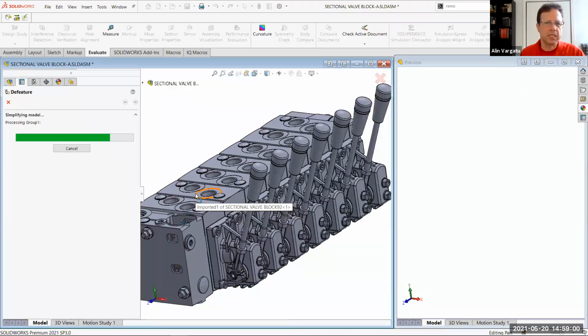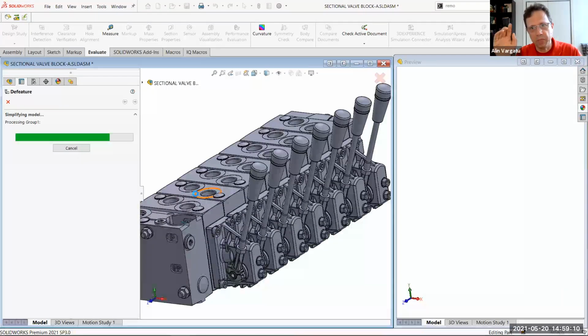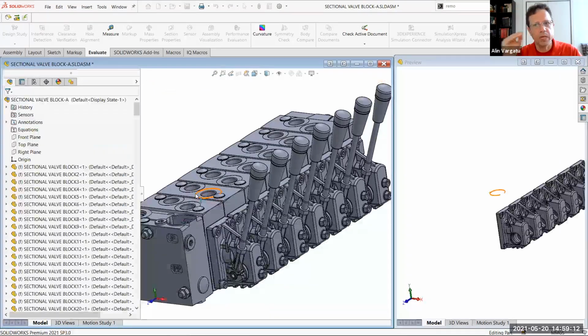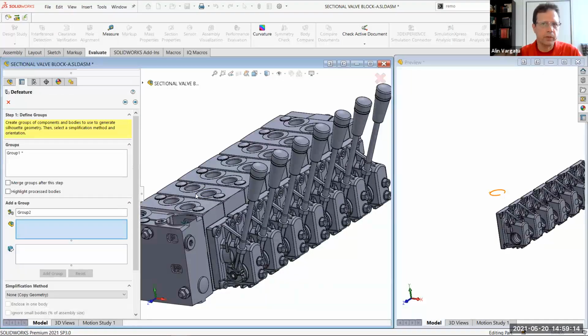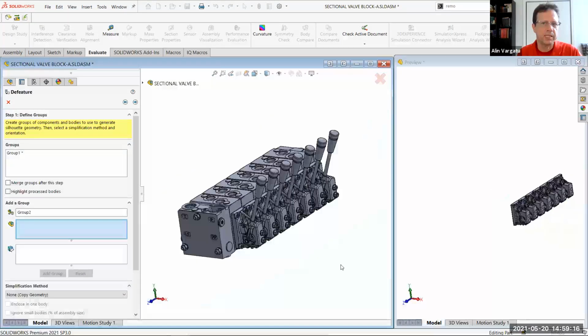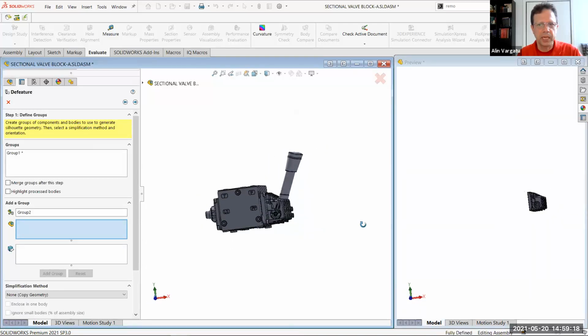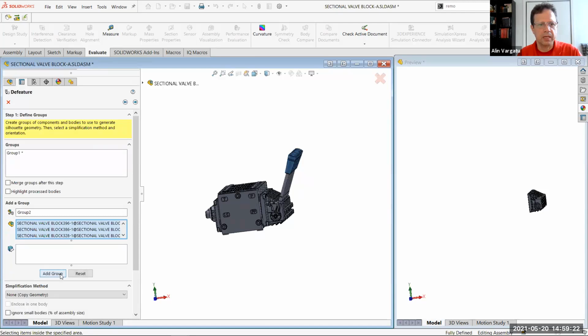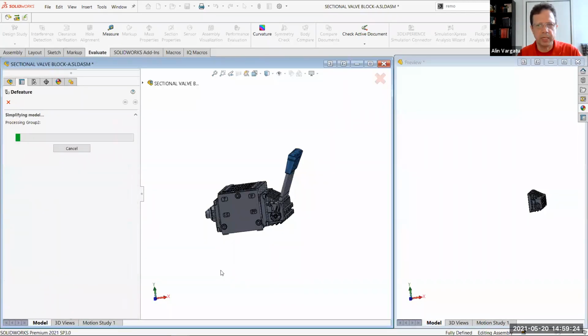So really the only thing SolidWorks does, it takes what I selected and it's simply gonna copy them as body into a multi-body part. Because many of you like to save assemblies as parts, which can be a good idea or can be the worst idea you had for your assembly performance, depending on how you do that save. This one is probably one of the best ways to do it. Let's say select all these guys, and again, I'm just simply gonna copy the geometry.